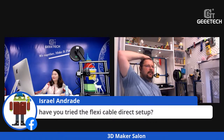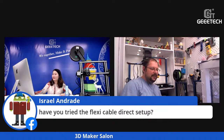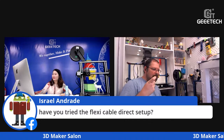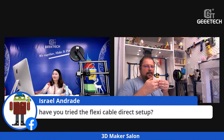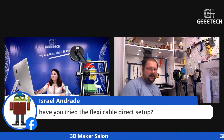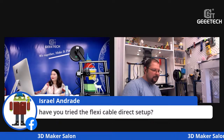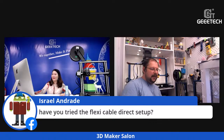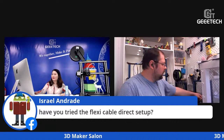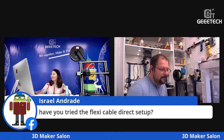I didn't try this because I think the flex cable is not the best choice for this use case scenario, because a flex cable will have very big movements, and if the flex cable is inserted in the port, this will always move while printing, and this can loosen with time. And if the wire loosens with time, this can cause a bad connection and also cause fires if it overheats. So on your printer, you must always check that the connections on all of your cables, but especially the heater cables from the extruder and from the bed and the power supply cables, are well connected. Okay, thank you.